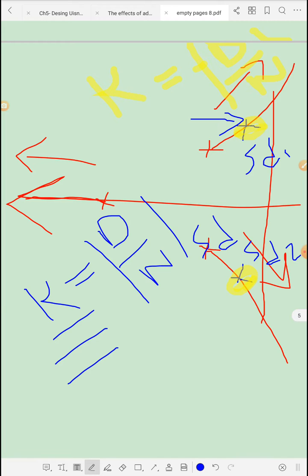Once we find this K, our design process is over, and this is what we mean by gain adjustment. The gain adjustment is used when the angle condition, odd multiples of 180, is satisfied, or the desired location of the closed loop poles that we need our system to pass through already lies on the root locus.